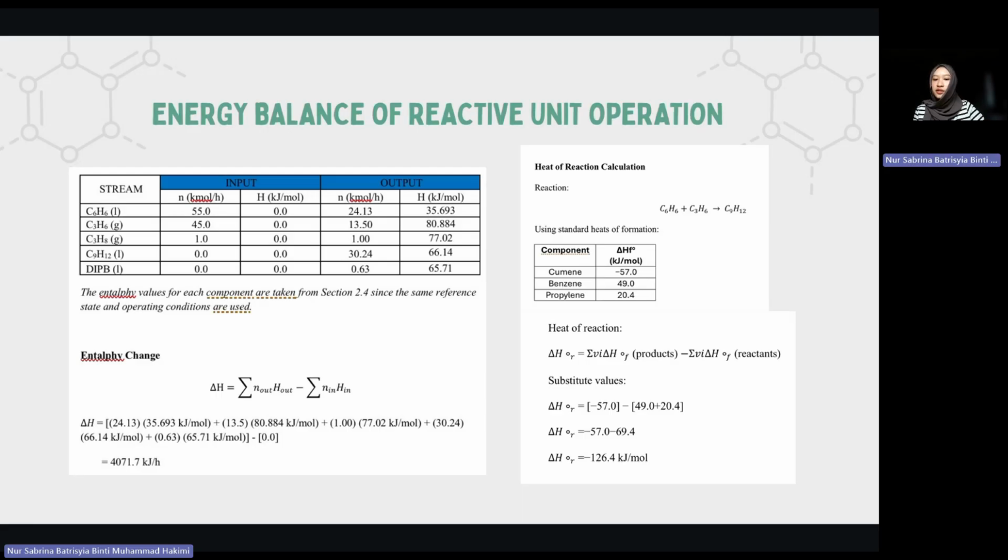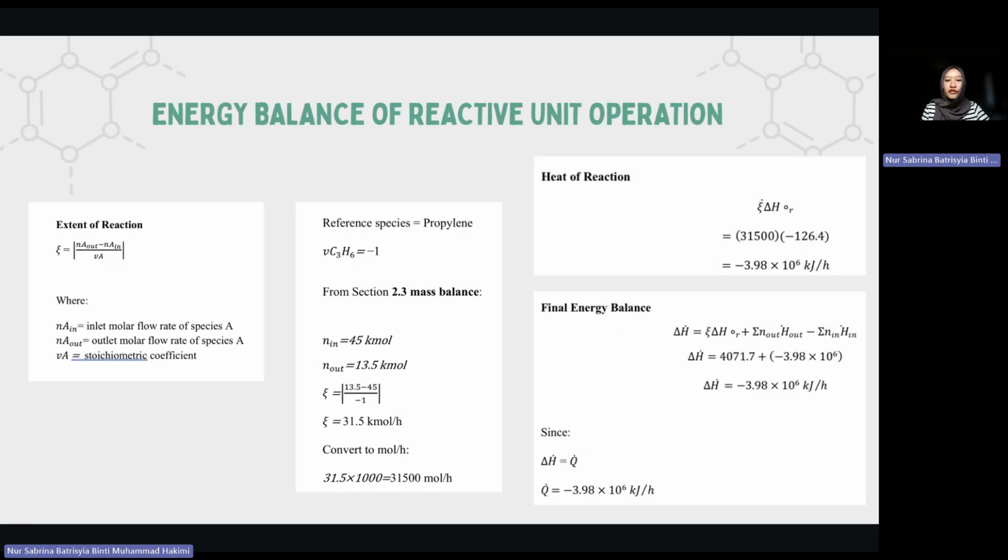So using these values, the heat of reaction was determined using the heat of formation method, showing that the reaction is exothermic. So finally, the extent of reaction was calculated using propylene as the reference species, and the overall energy balance determines the heat duty of the reactor, which represents the heat that must be removed to maintain the reactor